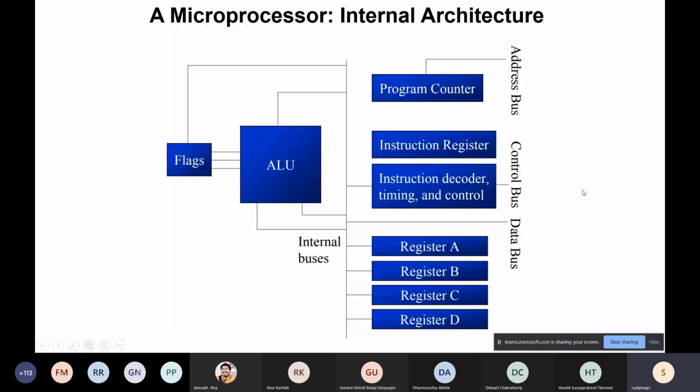If you are executing a large, very complex program, for that we prefer pipelining. That means there should be some internal queue of instructions maintained to speed up operation, such that locally they can transfer quickly, but globally, from outside the processor, from the memory, it takes longer. So it does prefetch. That means before execution or even before decoding, it prefetches the instruction. We'll see that with ARM.